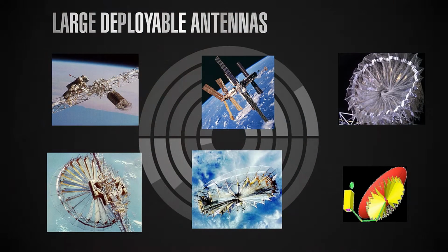One way to name this antenna is umbrella antenna or umbrella reflector, and they are also defined unfurlable, in the sense that with different types of mechanisms, when they are stowed, they look like rather small cylinders, and when they open, of course, the reflecting surface now is a mesh. It's a metallic mesh. It's no longer rigid. It's really like a tissue, but made out of thin wires.